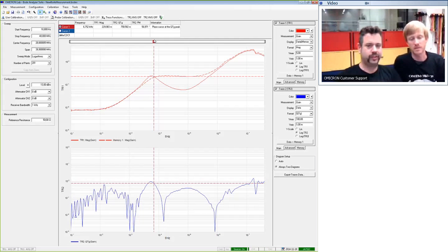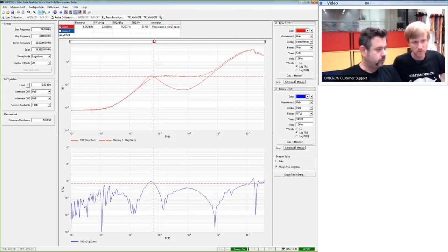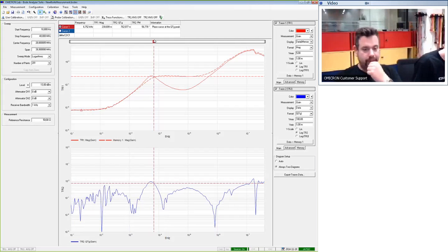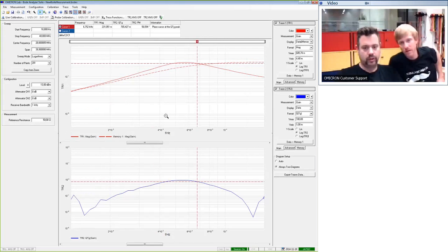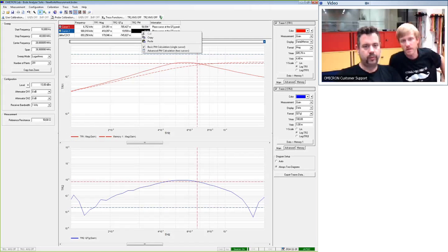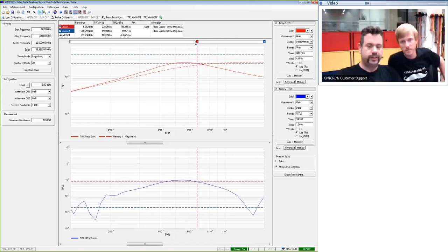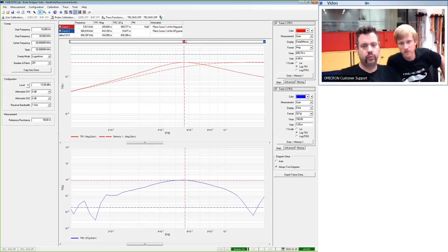First of all, we have seen that both peaks move down. This correlates with the fact that the 0 dB frequency, the frequency where the gain curve crosses the 0 dB line, is lower when both capacitors are activated. Now we will zoom in a little bit so that we get a better view on the maxima. Now I will activate both cursors and the advanced phase margin calculation. These peaks are still very close together. Nevertheless, we have to move the cursor into the center of each peak.